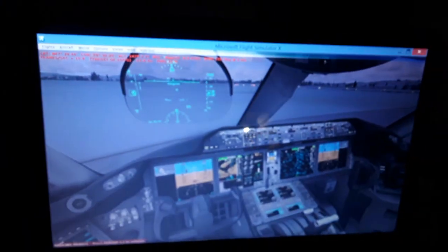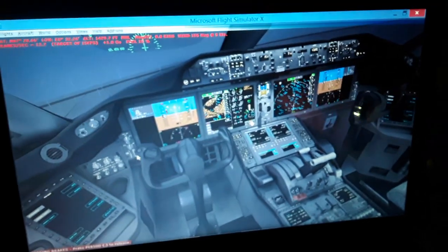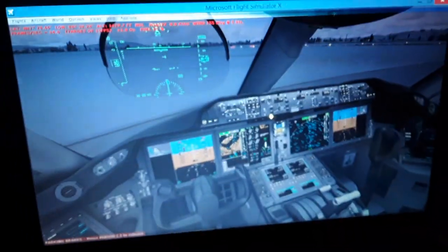So also when we fly we burn fuel and we change altitude in flight. This affects the center of gravity of the aircraft. The flight management computer recalculates this every second until we land again. So this is automatic, we don't need to do anything. We only need, for takeoff, to set up the flight management computer center of gravity and horizontal trim stabilizer. We're going to use 15 degrees of flaps, 4.25 degrees of horizontal trim stabilizer. We're going to have 23% of the mean aerodynamic chord position for the center of gravity and the angle of stall and where the maximum aerodynamic lift occurs.